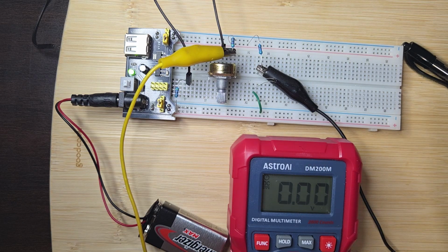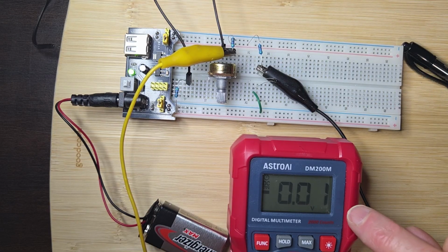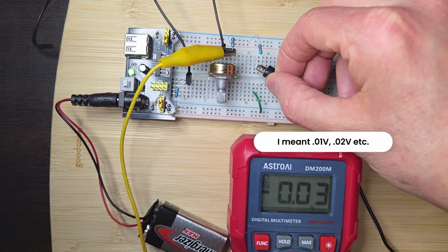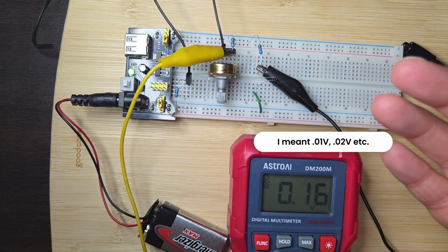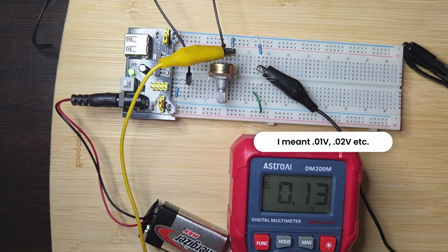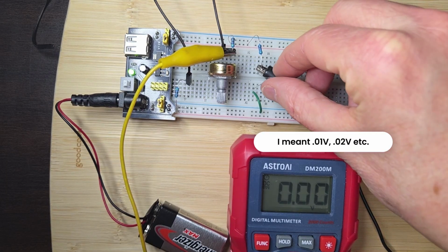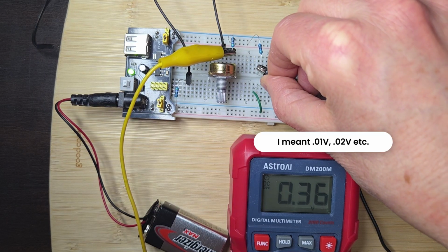So in this case, I'd have a thermometer, and you could plot whatever temperature it is. Let's say it's 70 degrees in the room. Well, 70 degrees would equal 0 volts, and then 71 degrees might equal 1 volt as you heat up. Then 2 volts might be 72 degrees, and 3 volts, 73 degrees, whatever. You could keep plotting that and actually build a little thermometer. But that's about as far as we'll go here, because that's all the stuff I have available to work with, and the video's running kind of long.